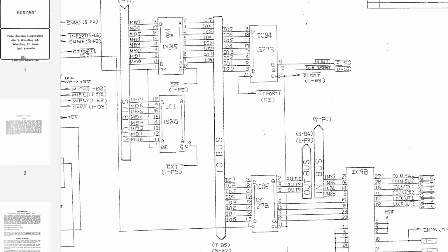Well, I found where the I/O bus originates. It's coming from a 74LS245 chip here, and that's a bidirectional buffer, which basically means it repeats and strengthens signals so you can connect more devices to something. If a CPU can only connect to a limited number of devices because the signals aren't strong enough, you can put one of these on there and connect additional devices to it without loading it down. And it's also switchable, so it can be enabled and disabled as needed.